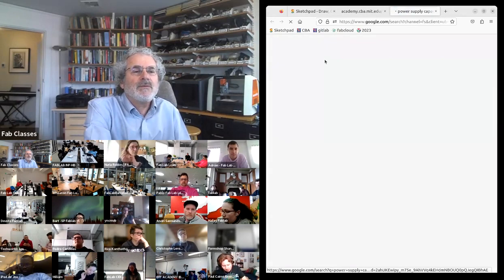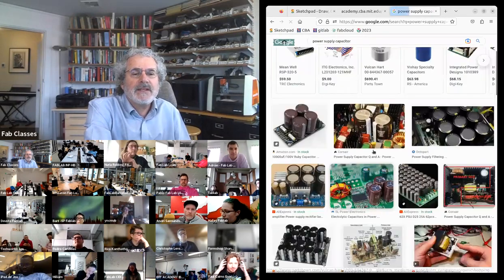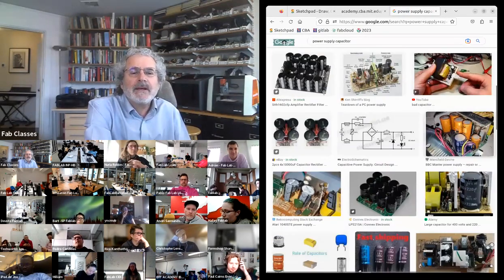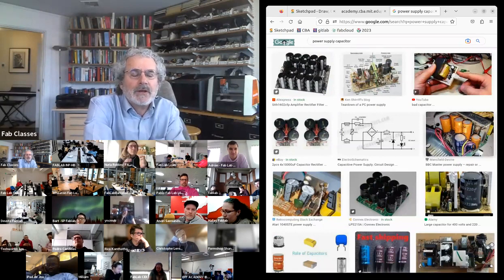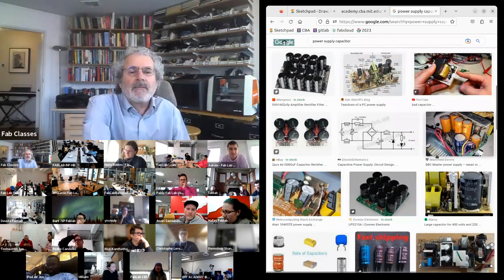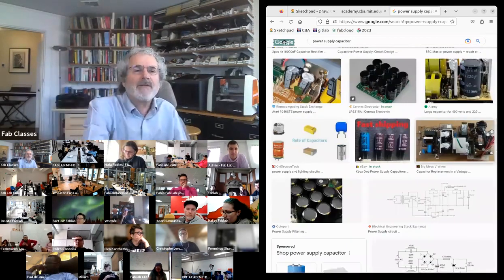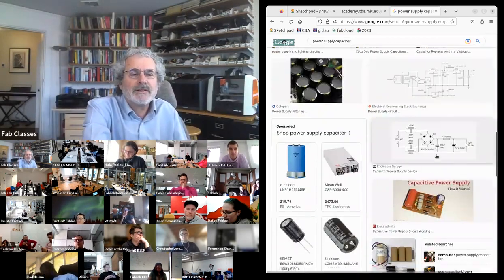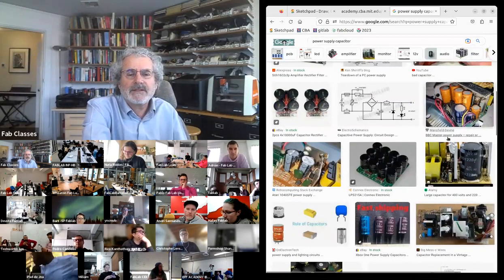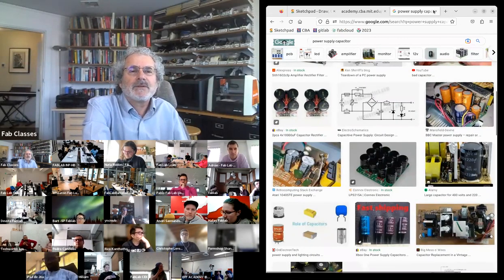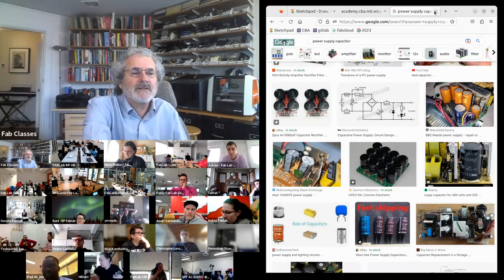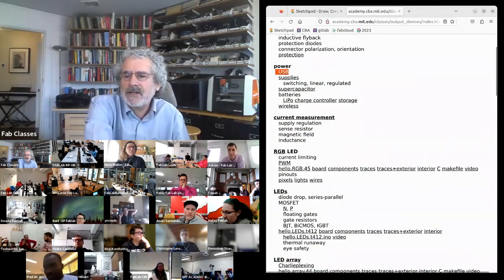So if you look in a power supply, you'll see really big capacitors. These aren't supercapacitors, but these handle much higher voltages with reasonable amounts of charge. And these big power supply capacitors can store substantial charge even when power is off. And so it's very easy to get a shock from them.